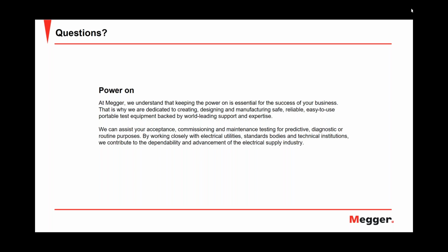And the other thing is simply, if you want to measure a face-to-face condition, you have to be connected face-to-face. If it's really from, let's say, A phase to B phase or something like that. But then keep in mind, Javier very well explained the limitations there. The TDR can see very low impedance situations, very high impedance situations. One example was this burned in the clear that Henning described, where the cable is pretty much destroyed at this point.